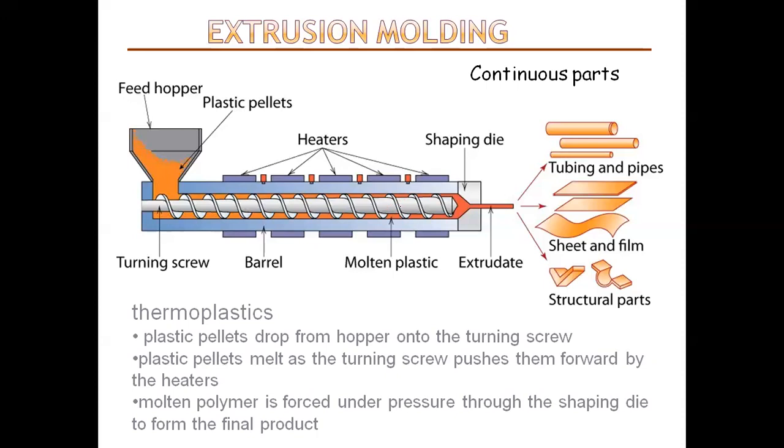If the heat generated is too much, they use a cooling fan to maintain temperature. If forced air cooling proves insufficient, then cast-in heater jackets are employed, and they generally use a closed loop of distilled water. Suppose it is not possible to control by a cooling fan, then a closed loop of water in heat exchange with a tower is provided to maintain the temperature.